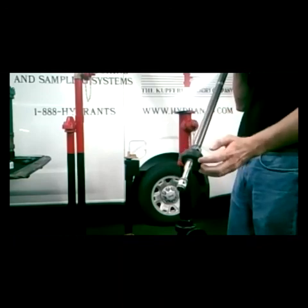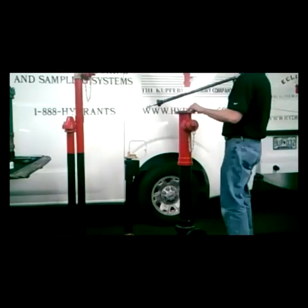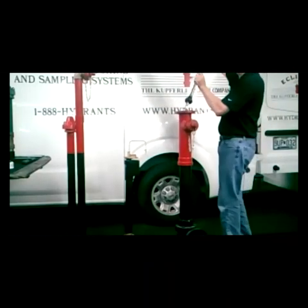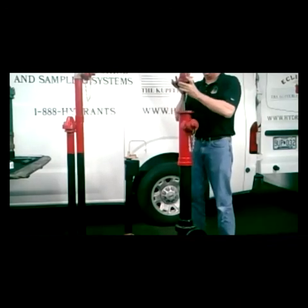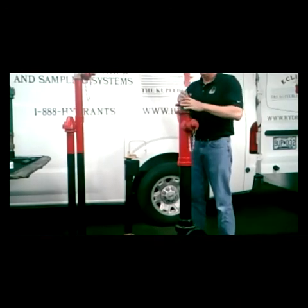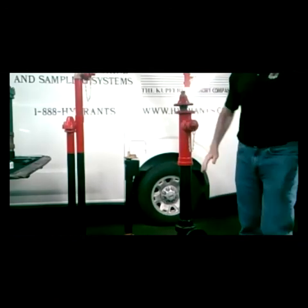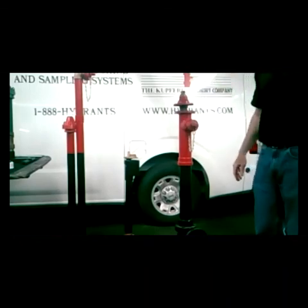It's a hydrant design that closes against the pressure. We close against the pressure, not with the pressure like a fire hydrant. So I don't need a seat ring, a seat wrench, or anything to try and get this thing apart. All right. So the number 2 is a very popular hydrant. People have been using these for a long, long time. We still have racks and racks of these that go out every day.